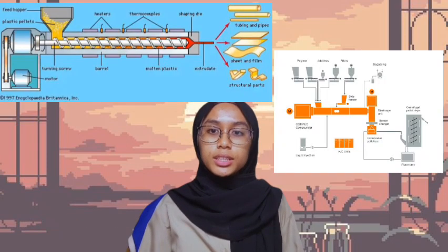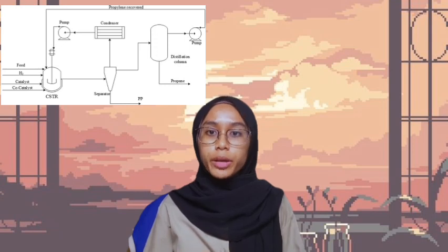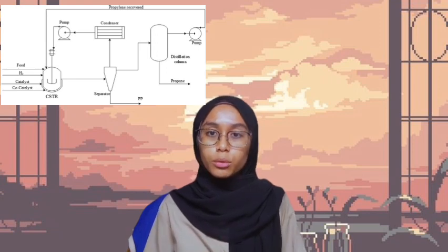The thermoplastic vulcanizates are prepared by mixing and shearing a thermoplastic polymer, a vulcanizable elastomer, and a curing agent. The vulcanizable elastomer is dynamically cured during the shearing and mixing and is intimately and uniformly dispersed as a particulate phase within a continuous phase of the thermoplastic polymer. The method of preparing the thermoplastic elastomer through dynamic vulcanization proposed in the present invention is as follows.